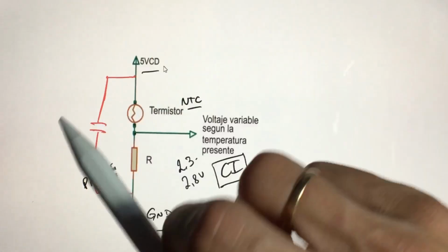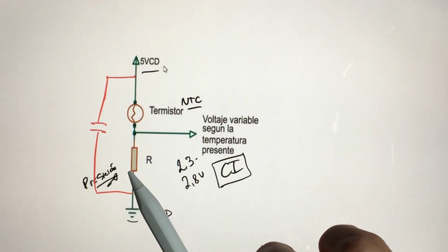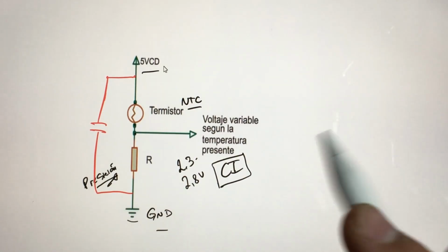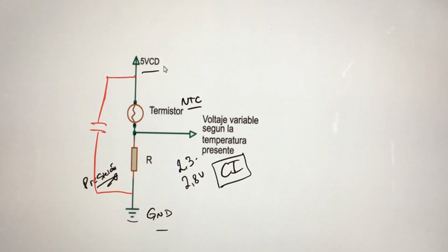Any error in the tracks, capacitors, or resistors in the temperature measurement circuit can cause the integrated circuit to mark a sensor error, even if the sensor is in good condition. That is why it is important to pay attention to that detail, as it may be that it shows us a temperature error or a temperature sensor error, but that the problem is not the sensor itself.